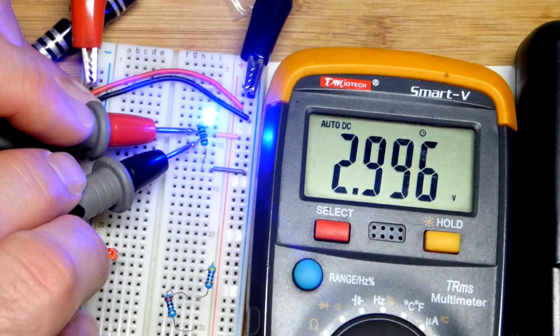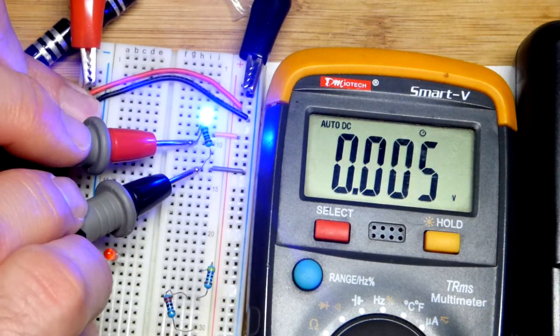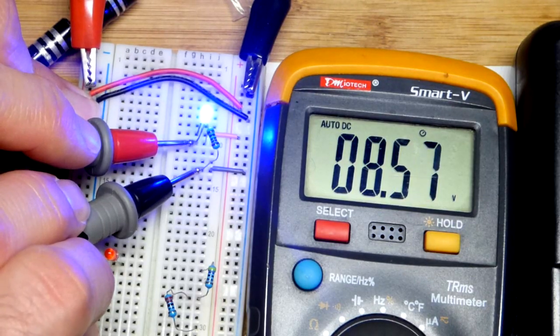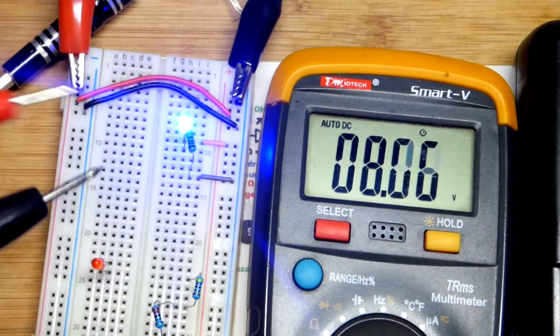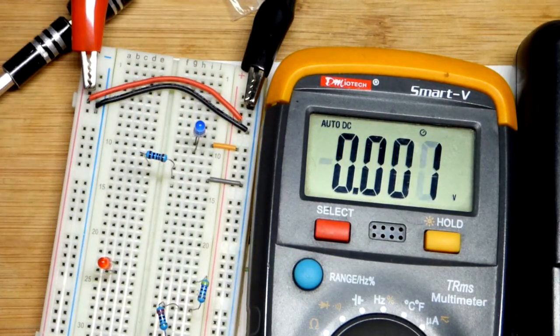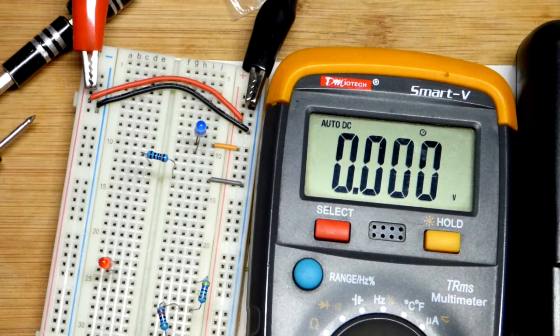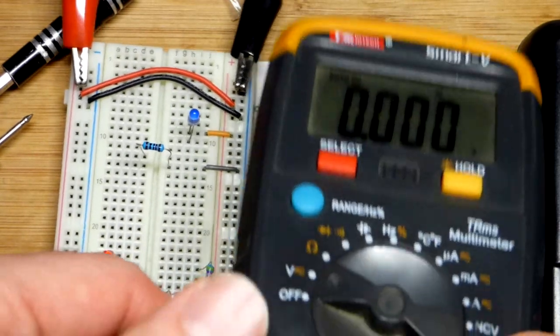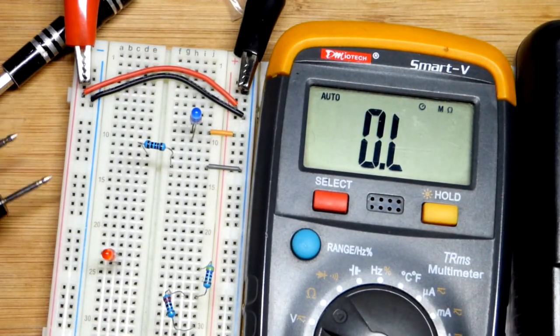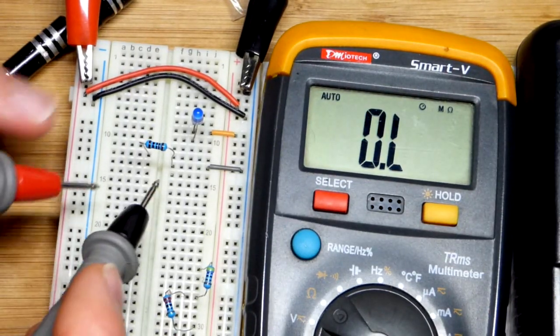So yeah, there we got about 3 volts across the blue LED, and leaving about 6 volts, or 9 volts I mean. That's right, we bumped it up to 12. So 12 subtract 3 is 9. Basic math right there. So we'll put that over there. And I do have one side of the resistor connected to the negative supply. We can still measure resistance right there. That's why I opened it up, just to get more practice measuring resistance.